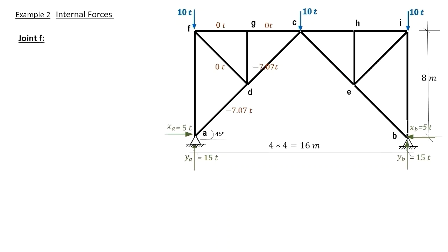To proceed with the internal forces, take joint F, and here we note that all internal forces are considered to be tension forces, as explained in previous lectures. Considering any member, say FG, the internal forces have arrows tending towards each other, which means that the internal force is a tension force, and the details are previously explained.